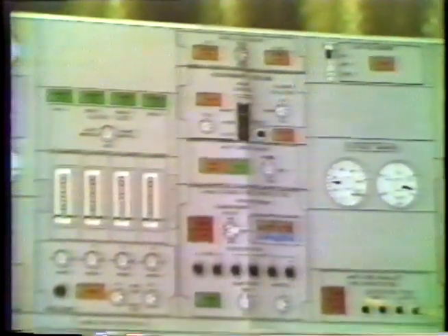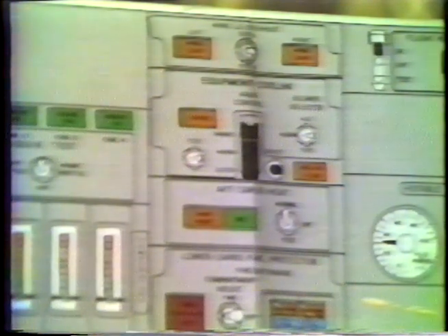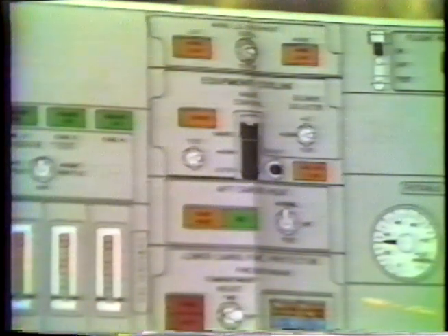Equipment cooling. A fairly important system. The airplane carries very, very expensive avionic equipment, and all of it is monitored by this little panel right here. The smoke light indicates there's smoke being generated in the lower portion of the fuselage. It also senses air being drawn across the equipment on the flight deck and the flight engineer's panel and the TR units and the battery charger, etc. Circuit breaker panel. So the smoke light coming on doesn't really tell you exactly where it is, but there is smoke in the air that's being exhausted across the equipment.